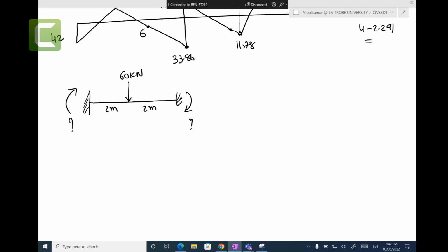Yes, so we need to solve. There is the force method. Degree of indeterminacy is how much? Let's say axial is not there. 1, 2, force 2 unknowns. 4 take away 2, degree of indeterminacy is 2. We can solve, right? We can remove this support, we make it this one, and we remove these supports. Apply the load, find the displacements, and put this reaction force up, and so on. Right? Yep. So the question is here. Let's solve this example by ourselves, and then we compare our answers with the table. Okay, I will solve as well, and I'll give you the solutions.